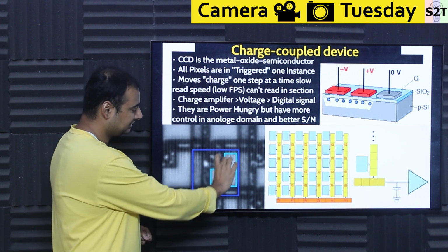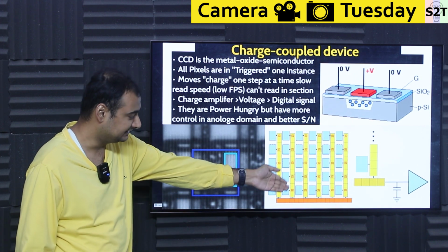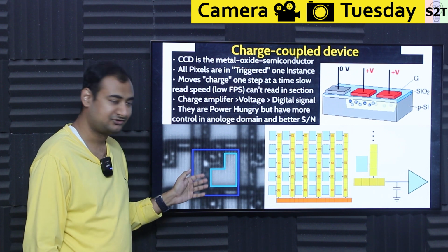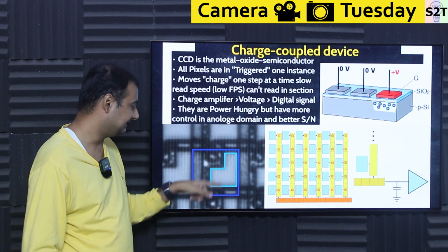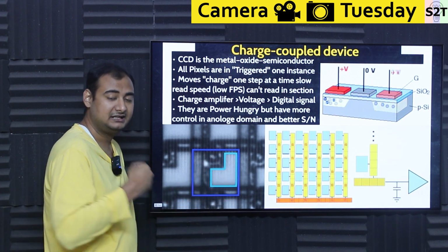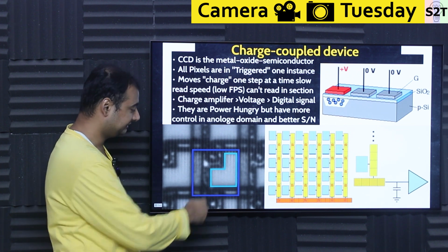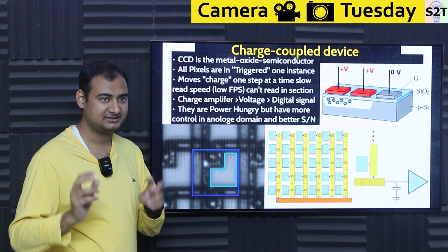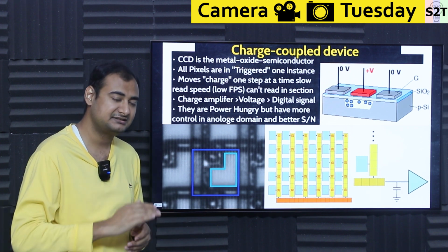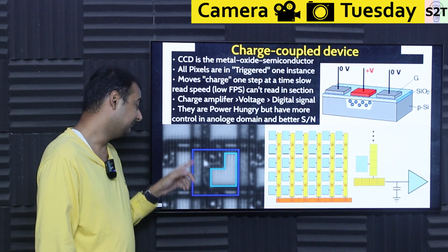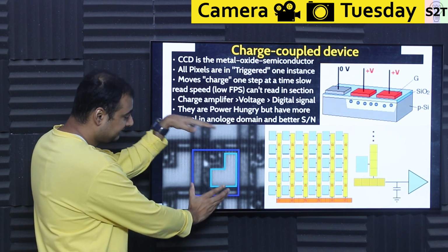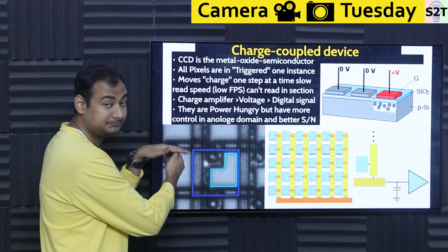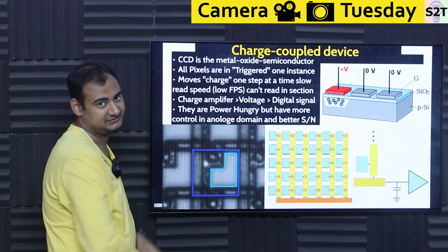True pixel is only a small area in that. Now, why is that? Well, all these things also have to be there: the wiring, the electronics, the charge capacitor, all of that. So you have a pixel, and then you have what we classify as active area. This is the primary reason why we have to add what we classify as micro lenses on top of this sensor array. All sensor arrays have micro lenses. Micro lenses' primary job is to try to focus the light that is falling on the pixel into the active pixel.